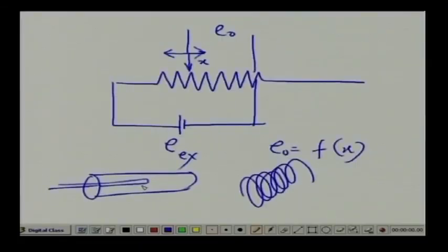good, extremely high, because in this case there is no question of the windings on the outside; it does not matter how fine and how close those windings are, because the resolution here depends on the magnetic linkage between the two. It does not depend on the physical position or the physical number of coils which get in touch with the wiper. So, that is a great advantage of the LVDT.